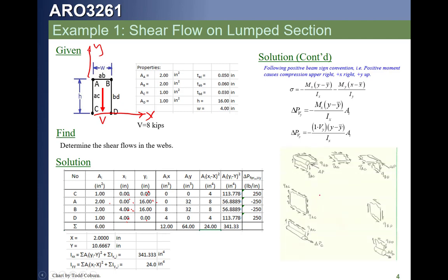We then can walk through the segment one piece at a time, and the way we do that is like this. We pick a free edge like this one down here, and we draw our delta forces. In fact, it's useful to first draw all of our little unit areas, and from this column of the table we'll put what they are. So at area C we've got tension, so we'd put our little tension 250, and at A we have compression. That's this 250 of compression going like this. The next one's all in compression also, and the next one's in tension.